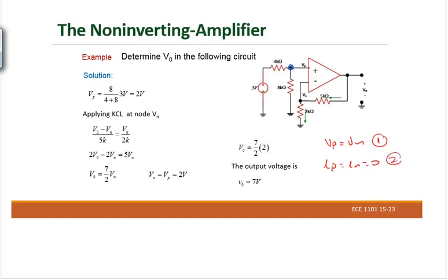So can I find the VP value? Can I say voltage division? Yes. So number one, can I say VP? I'm going to change the color here, like blue. Okay. VP will be equal voltage division. I think it's easy, I can write 8K divided by 4K plus 8K times 3 volts, which will be equal, I think, 2 volts right there, if you do it.